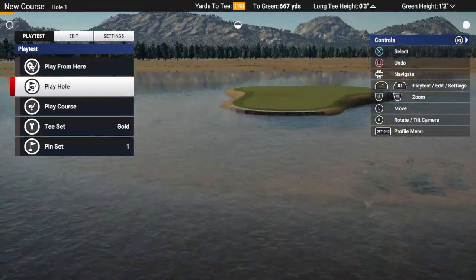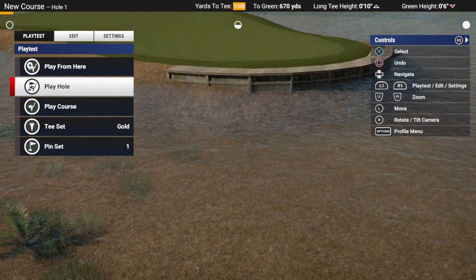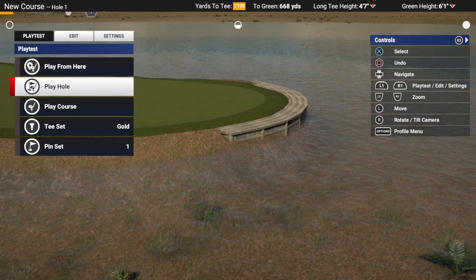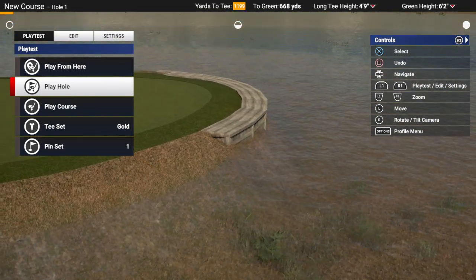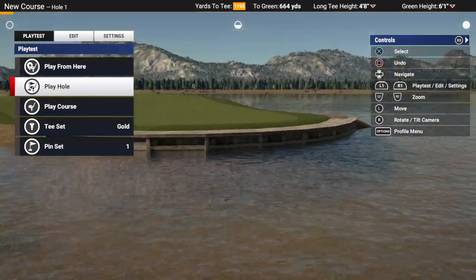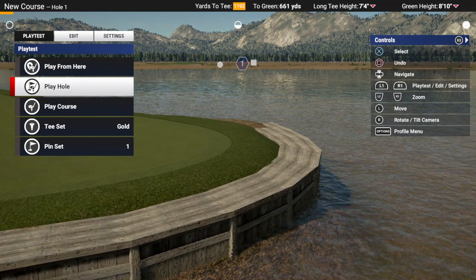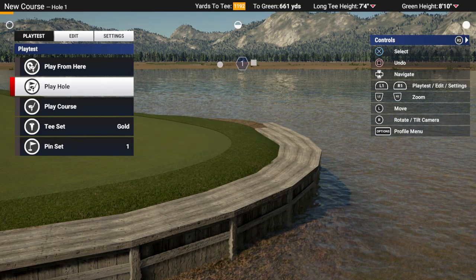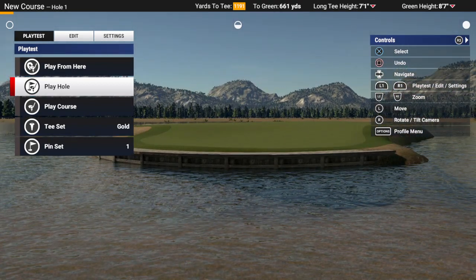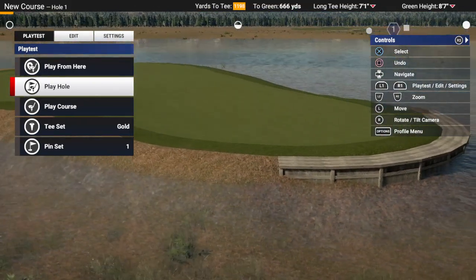This is kind of an advanced, maybe a 201 or 202 level class. I'm going to assume a little more experienced designers are looking at this, so you're already probably familiar with the standard three-layer technique of retaining wall, trying to get a clean look where the back of the surface, be it the green or whatever terrain, meshes with the back of the retaining wall, so when you look at it water level, there's no jagginess, and you can see retaining wall and none of the terrain.